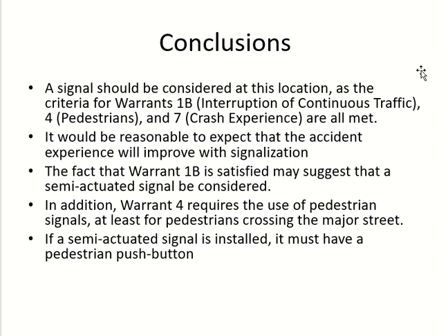That is A. B says that the major road volume is so high that if you keep it unsignalized, the minor road will not get a chance to enter. So that also means what? That the major road has very, very high volume and the minor road compared to that has very, very low volume. Okay, so that's why they are saying that maybe you should apply a signal which is semi-actuated.